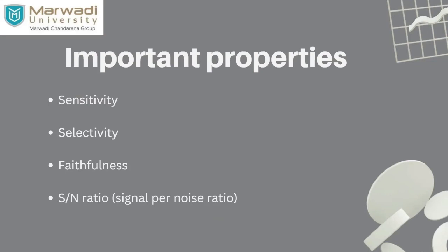So the circuit has to be sensitive. Then selectivity: as we know, from the local oscillator the user can control or give the frequency by their choice. So we have to select the frequency according to that; f0 minus fs is the proper value of frequency as we want.